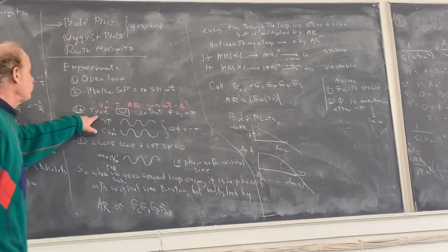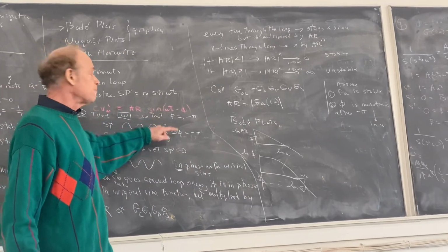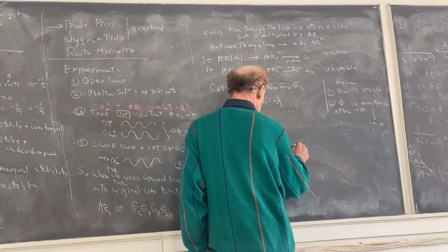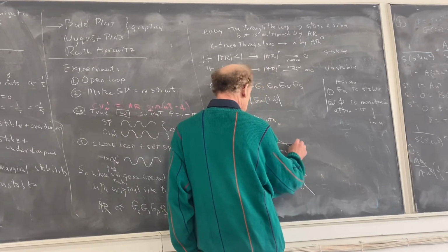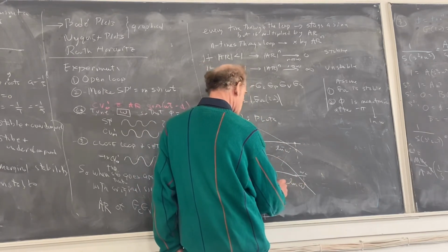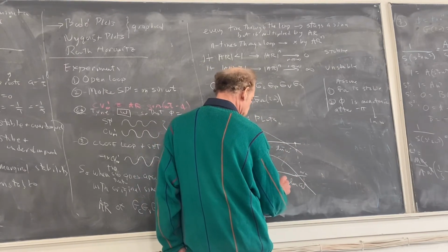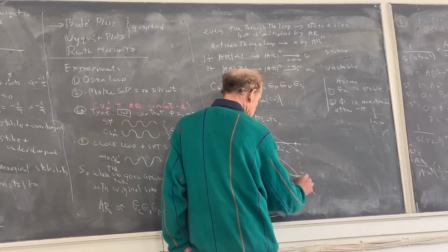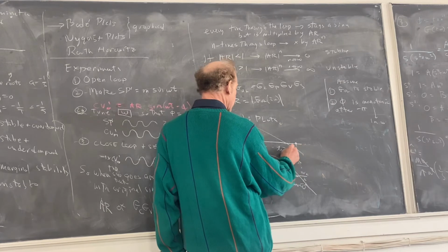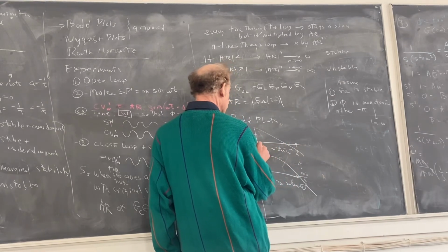That's exactly tuning omega so that phi is minus pi. And then at this value of omega critical, I would go up here and ask, what is the amplitude ratio? So at minus pi, I go this way, look for omega critical, go up, find, and then go across here to find the actual amplitude ratio.